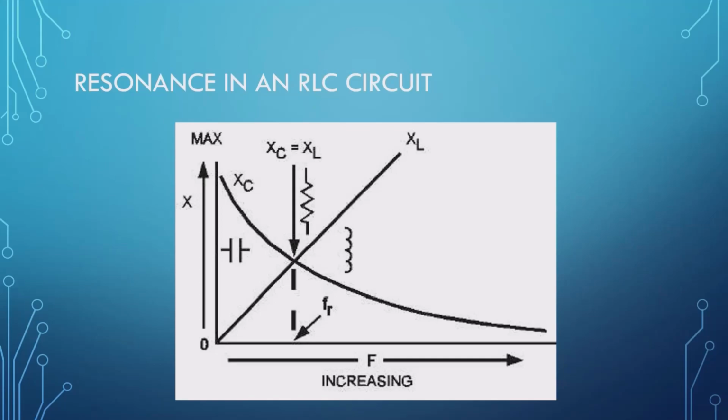With an inductor, it acts the opposite. At the lower frequency, it acts as a short, and until the frequency gets closer and closer to resonance, it'll continue to conduct the signal. Once it starts to go beyond the resonant frequency, it actually tends to start increasing the impedance, which will then start to degrade the output of the signal and will start to block the signal. So that's kind of how the two work together in conjunction.